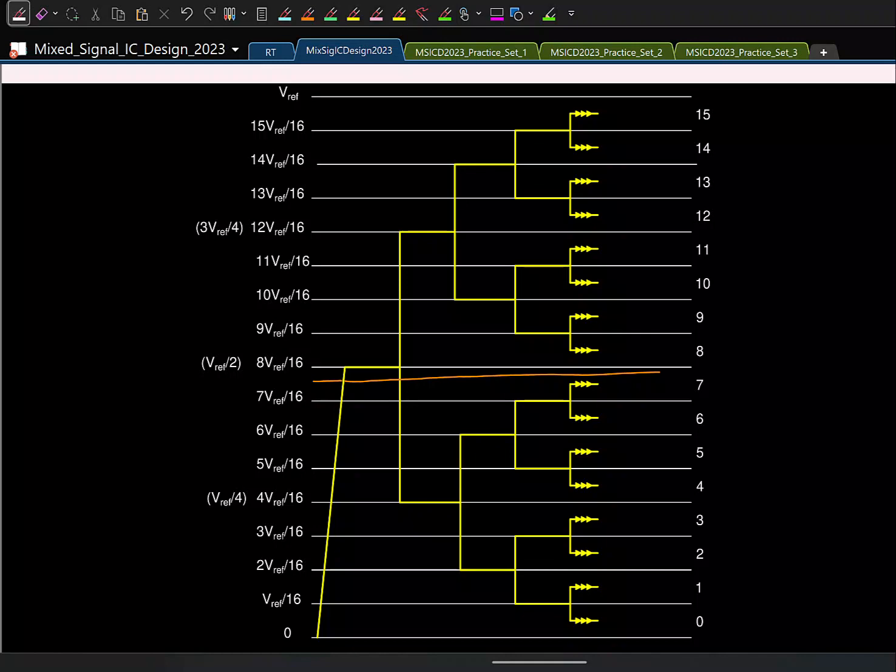So which means if I have a 4-bit SAR, nominally I should do 4 comparisons. But if I were to correct for an error, how many comparisons should I make? At least 5. So I should do more than 4 conversions or comparisons. This is usually called redundancy.